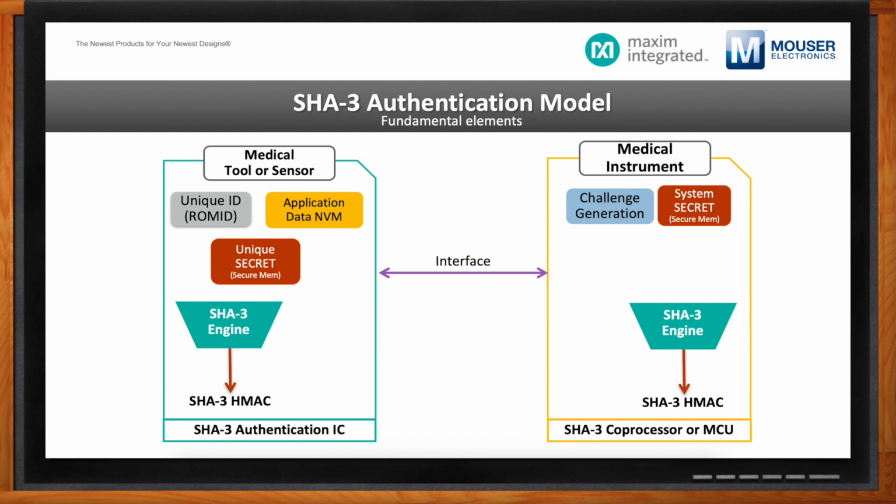Over on the medical instrument side, we're going to have a lot of the same components. We're certainly going to have the ability to do SHA-3 math. We're going to have a system secret now. So we've got a unique secret over in the tool. We're going to have a system secret over in the medical instrument, which is different than that unique secret in the tool, and that's important coming up. We also have the ability within the instrument to generate what we'll call a challenge.